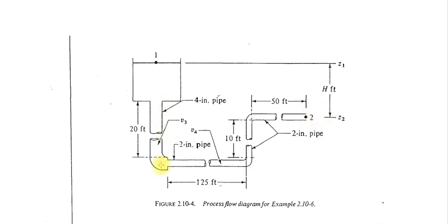And here you have different types of fittings. These three are the 90 degree fittings. You have one sudden contraction also here. Here again, when the water is entering from this tank to this pipe, you have a sudden contraction. At this pipe also you have a sudden contraction again. Then you have different sizes of pipe here. Then you have the friction losses due to the solid pipe. So you have the friction losses in this problem. You have the losses due to the elbow.